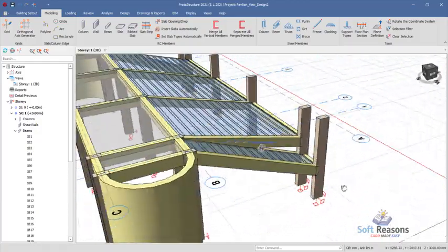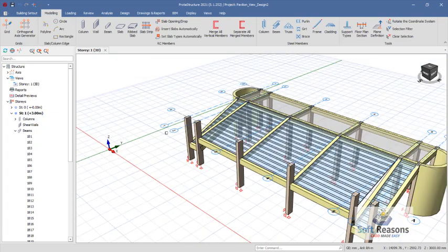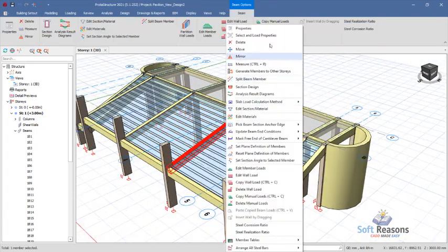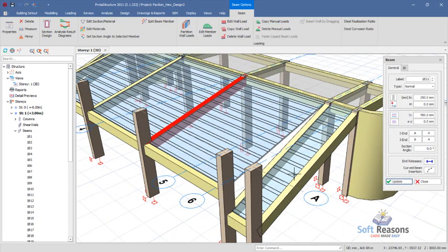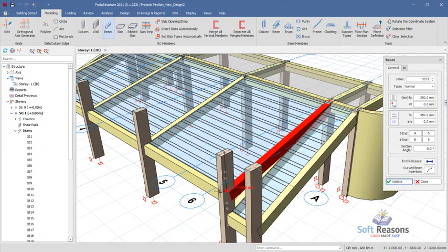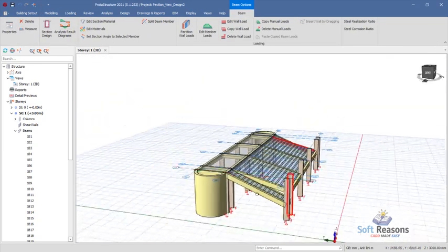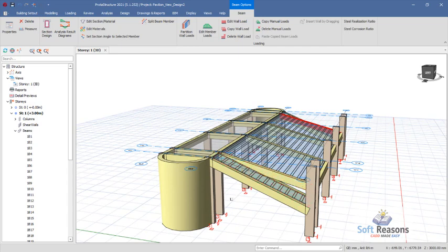You can see. Alright, so we can do that over to these provisions. Use the property of this beam, and then click on this property, pick the first point right there, pick the second point to have the beam placed, just like that. Okay, alright, so at this point we can now generate this to other floors successfully.